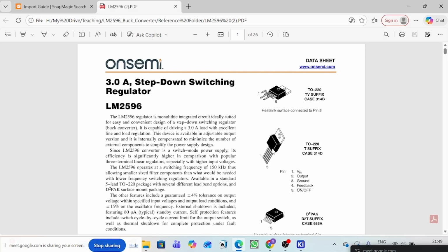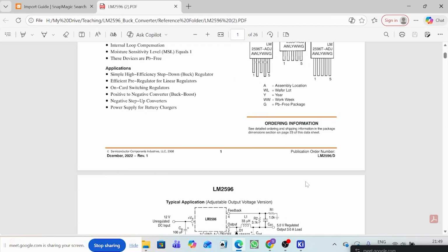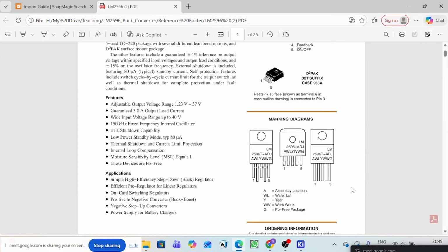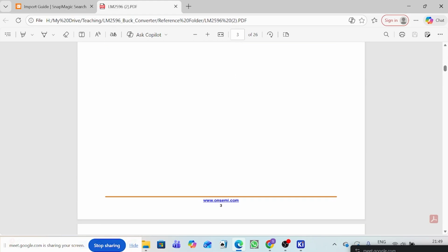If you want the through-hole, then check whether this one or this one is easily available in the market. You can choose out of these two for the through-hole, and there is only one available for the assembly, so for the assembly, go to this one. And if these are not available in your KiCad or in your SnapEDA, then we want to create those. So how can we create those?